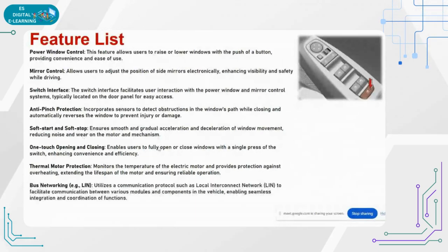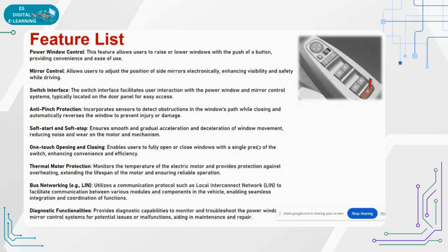And moreover the communication. We usually operate with the LIN protocols and the CAN protocols. Whenever a problem comes, you are able to see it on the cluster. Similarly, when you go to the garage with the vehicle, you need to find the problem with the help of diagnostics. We need to see the communication messages and the diagnostics for all the features, identify the problem, and remove it. So this is the feature list that we usually work on for cars.